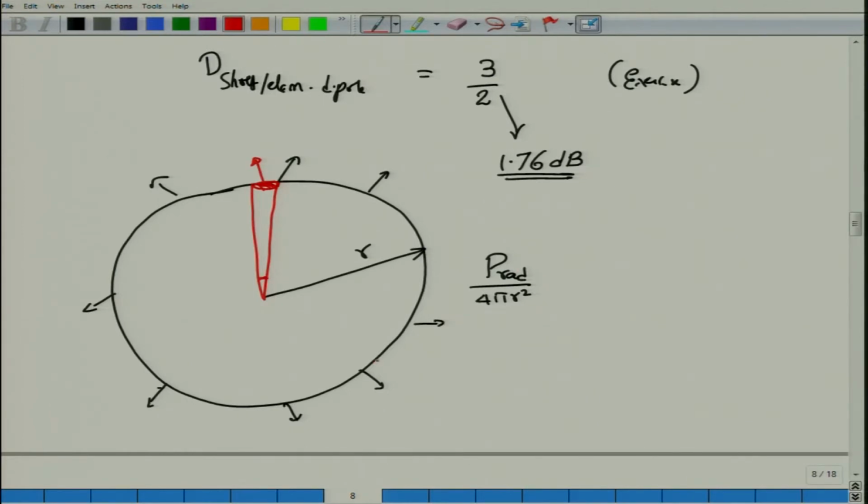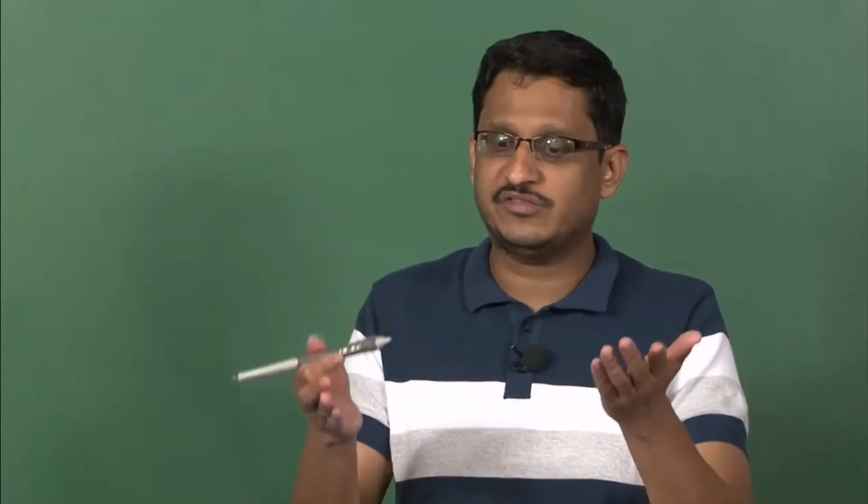So obviously this black curve is not at all directive because there is no direction specific region where the electromagnetic energy is concentrated, whereas in that red curve, which actually represents your antenna design, radiates in a particular cone of an angle. So there is a high directivity associated with that. Okay. Let us do a simple example.